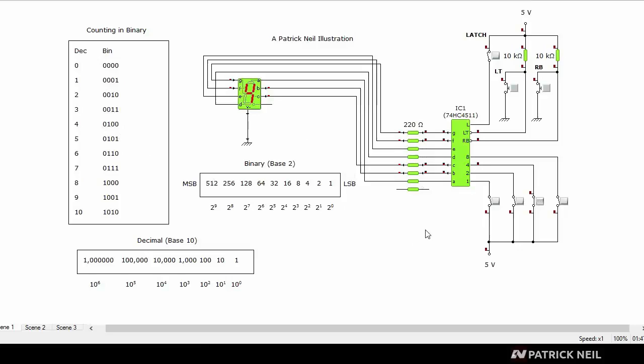Now I don't know if you're taking notice to what's going on here, but you have to know the specific sequence to put these codes on these pins. What I mean is, for example, the code for 4 is low, low, high, low. And pay attention to the fact that I'm starting from my right and moving to my left. Now, we need to put that code as input to the decoder.